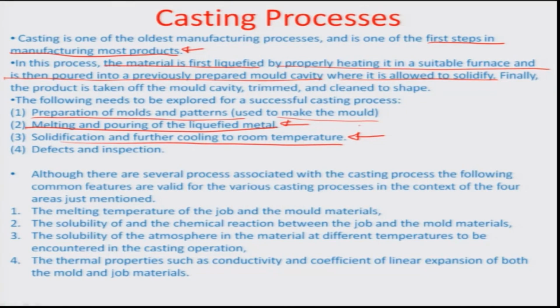And one of the reasons why this is important is that we assume that most of the metal goes into the mold from the gate region as liquid metal. And so once the liquid is now stationed inside the mold, and you have obtained an indication from the other side, which is also known as the riser side, that the metal has fully filled the cavity, there is going to be heat transfer of this metal to the casting walls. Pressure die casting, where a metal mold is what is basically used for filling of the metal.